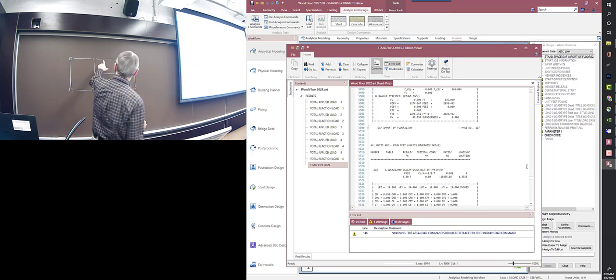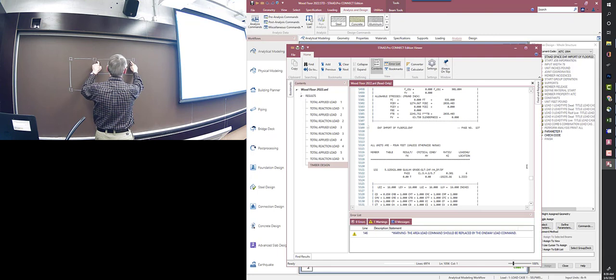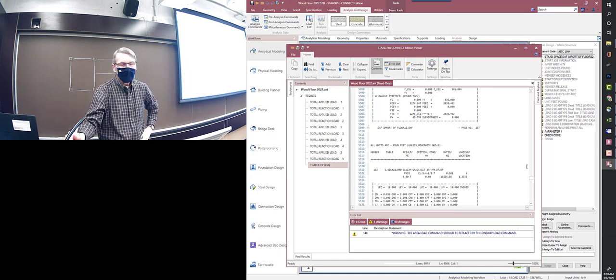Like on these beams, we've broken them up into how many segments. Every space between the joists is a separate beam. Although we grouped it into one, when it does the code check, you get a separate reading for each one. I was thinking, let's just look at the critical ones in the center.